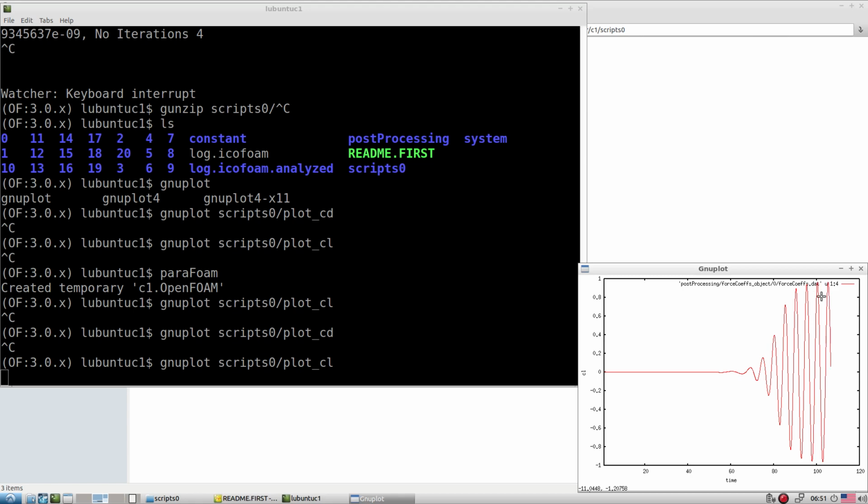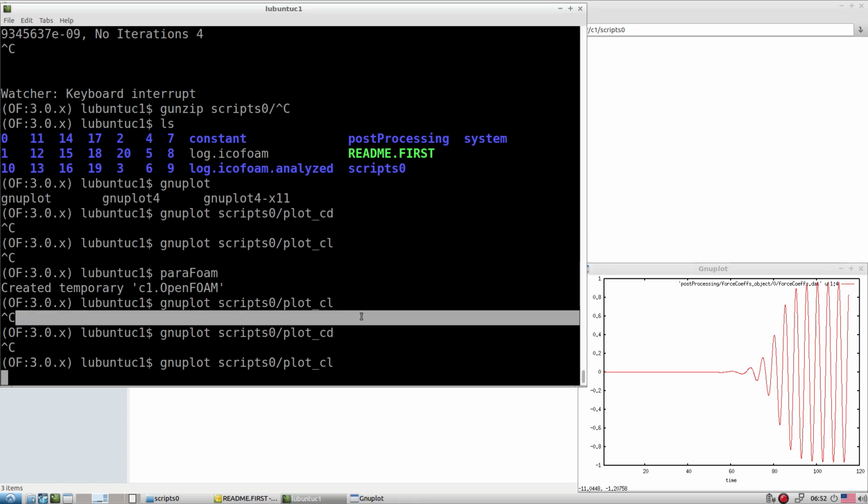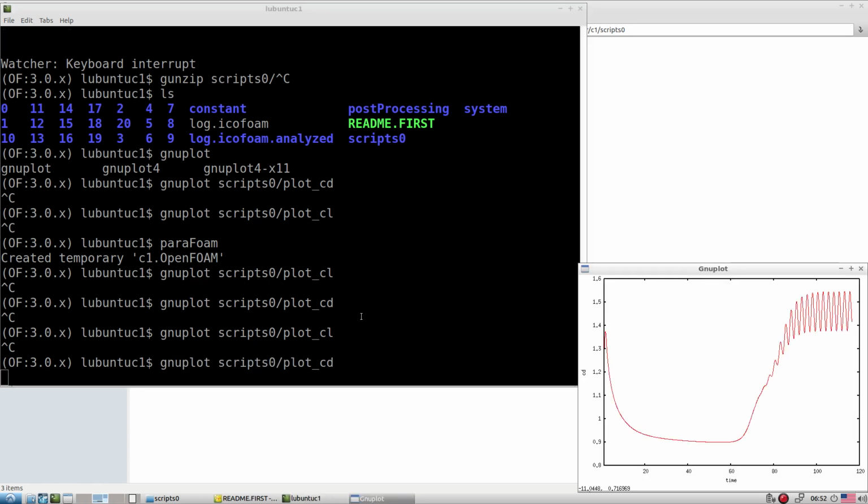It is not called steady state, but it is called a dynamic steady state. Why is it called dynamic steady state? Because now we have repeated vortices of the same size and with the same frequency departing from the surface of the circular cylinder. Look, now it has almost become uniform. Let's explore the CD as well. Yes, CD is also almost mature.